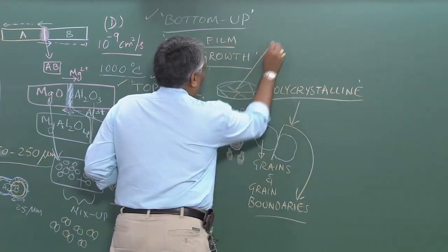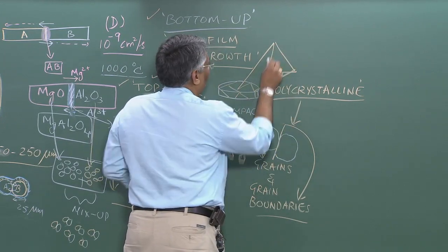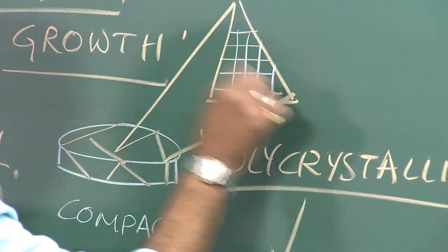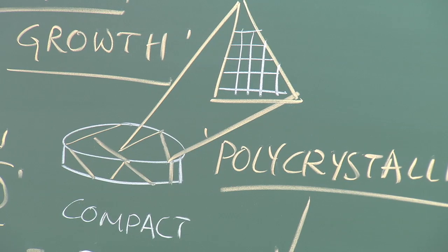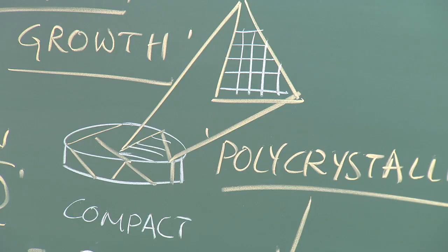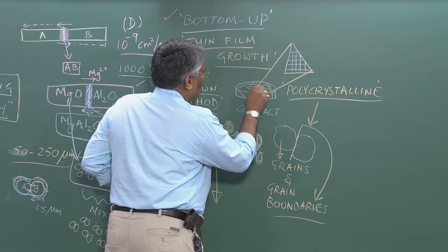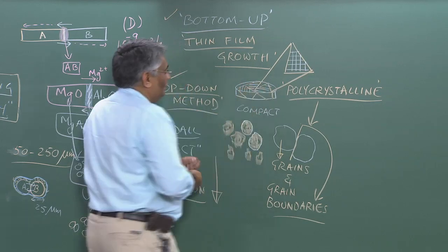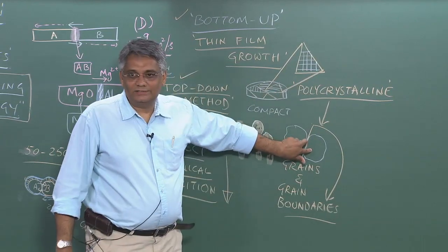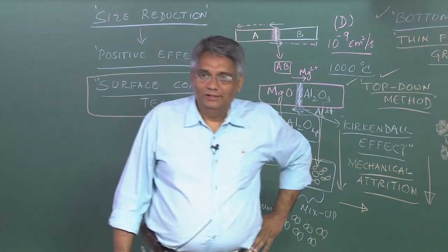So if you look at the microscopic view of a grain, you have perfectly aligned, arranged unit cells, right? So a grain is a single crystal in itself, okay? Each of these grains, and the neighboring grain also is a single crystal, but the problem is the grain boundary, the region that separates two single crystalline regions, need not be single crystalline. So the grain boundary is a defect region.